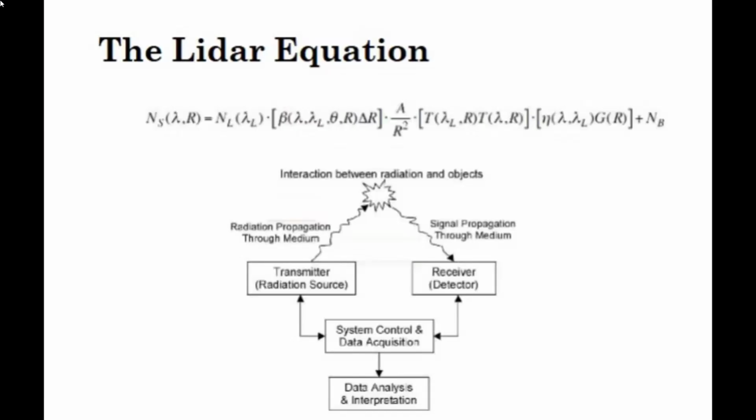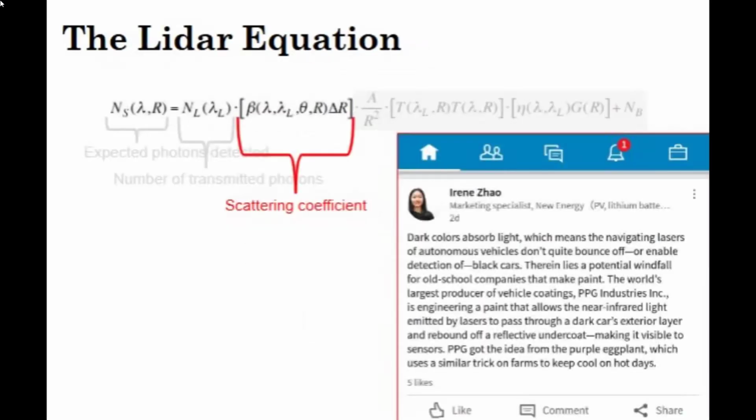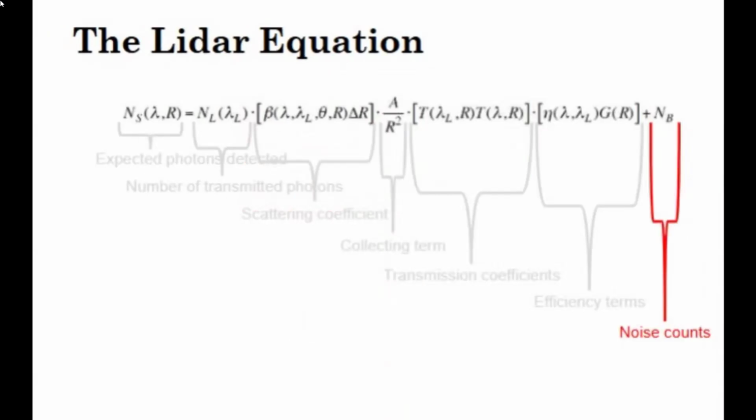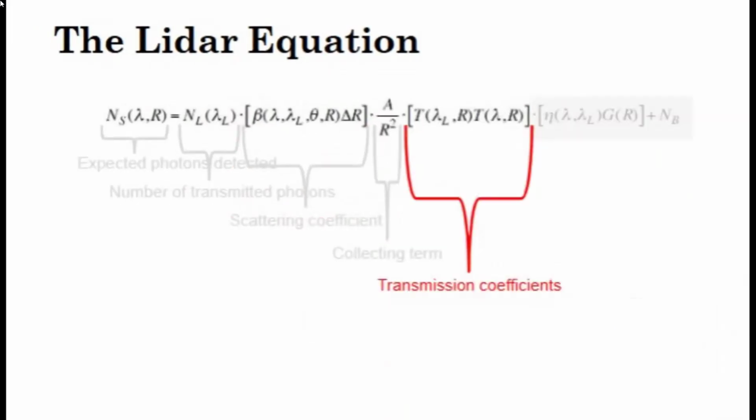This setup is grounded in the principles of the LiDAR equation, which relates received power to range, surface reflectivity, and system parameters. While my sensor doesn't use time of flight, the core idea still applies. The accuracy and quality of my 3D measurements depend on the reflectivity of the lamp surface, specifically the glass, ambient light, interference, and the geometry of the laser-camera setup.